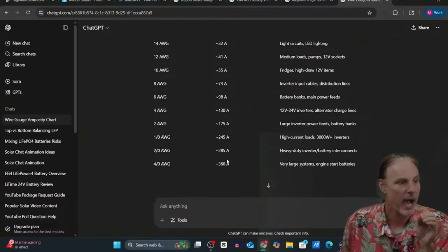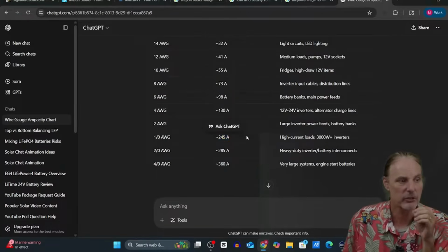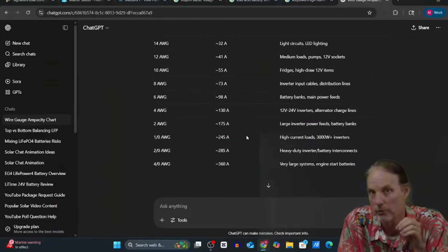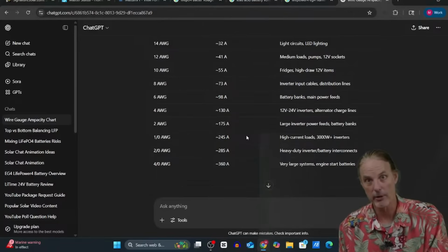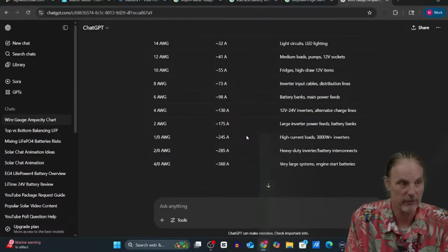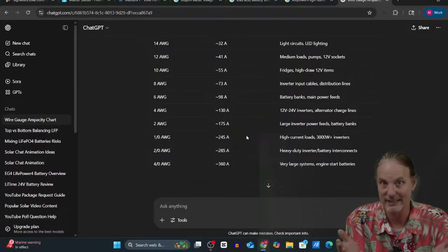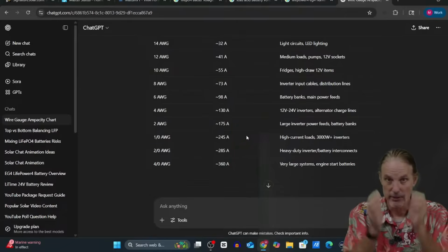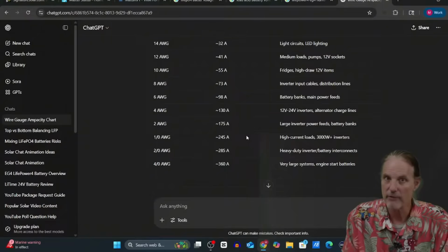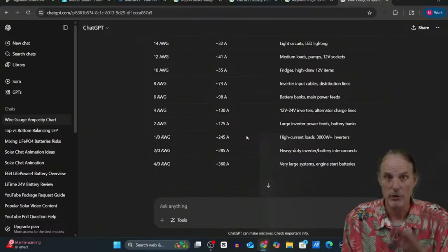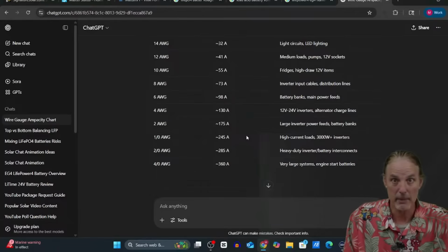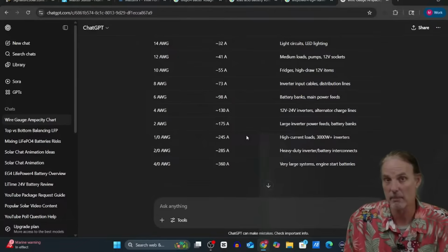with. So I have got one wire in my RV, and it can support about 245, 250 amps. Therefore, a 200 amp system with a 250 amp fuse would be perfectly safe. Now, I cannot stress this enough, that this is very, very dangerous if you get this wrong and you're putting in these giant BMSs and you're fusing it based on the BMSs.